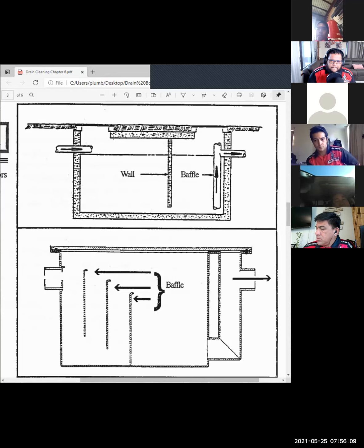That is a modern-day wonderful grease trap, and it'll go beyond the capacities of the top vertical one on this drawing, because they're designed to catch more and a thicker mantle and separate even faster because of the way they baffle out. But you should always be able to understand this top picture.